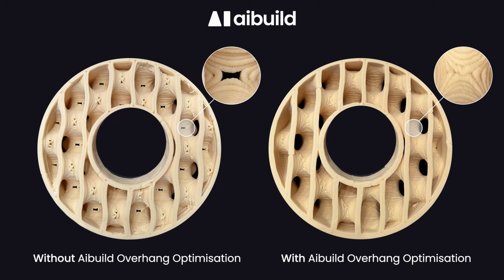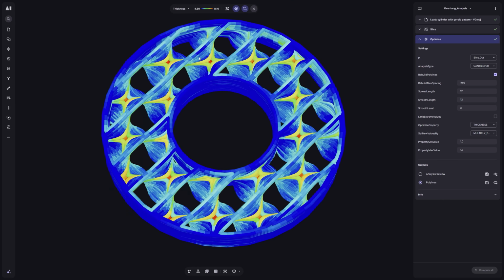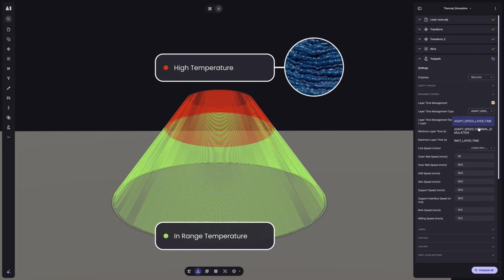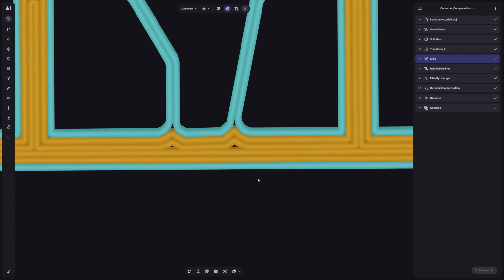So if we think about specific applications, maybe I could start with the one that is our biggest expertise, that of large-scale additive manufacturing. A great benefit of the Aibuild OS is that it can handle the whole cycle of design to manufacturing. The user can upload the design, and then it can be optimized by the agent for printability and specified criteria, then passed into the Aibuild CAM, where it will slice it, finding the optimum slicing strategy, tweak the settings, and then evaluate the results and optimize them based on different quality metrics, and then finally generate the toolpath for it.